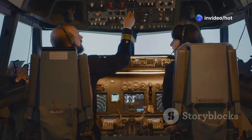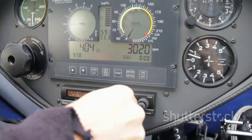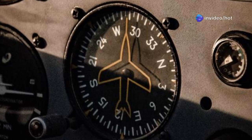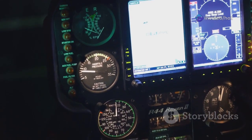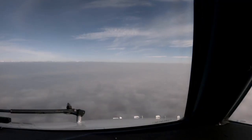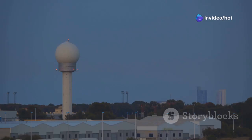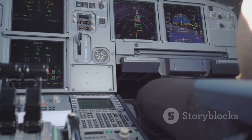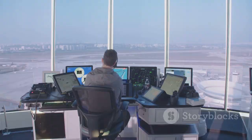To solve this, the concept of flight levels was introduced. A flight level is a standard pressure altitude. Aircraft altimeters can be set to a standard pressure. This standard is 1013.25 hectopascals, or, in North America, 29.92 inches of mercury. When an altimeter is set to this standard, it reads flight levels. Flight level 350 means 35,000 feet on this standard setting. This creates a common reference for all aircraft, ensuring everyone is using the same ruler. Using a standard setting simplifies things greatly. This uniformity is critical for safety.